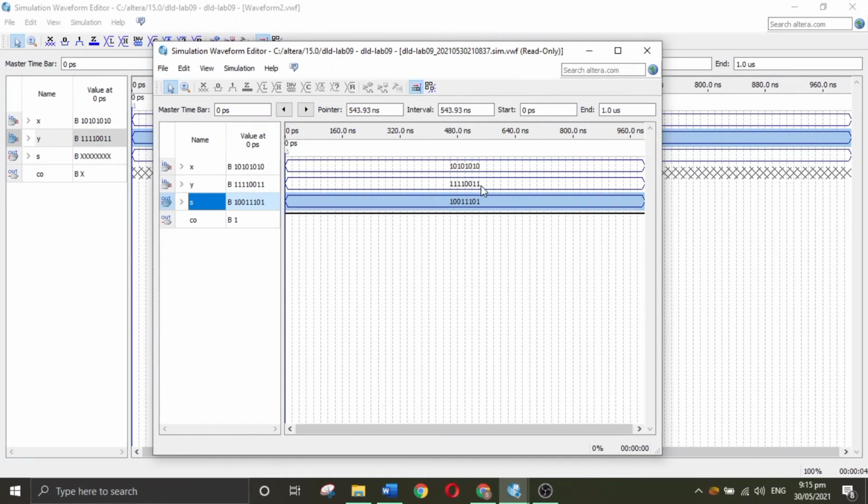This is the output, you can see. For example, this is 1 and 0. If I add 1 and 0, then the output will be 1, and then 1 plus 1 is equal to 0 and carry 1, and 1 plus 0 is equal to 1. So this is showing that at the end it is 1 1. So the carry output will be 1, that is exceeding the 8-bit value. This will go towards the carry out.